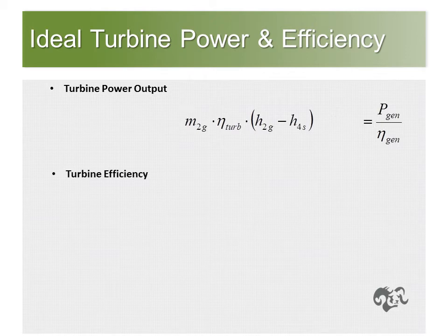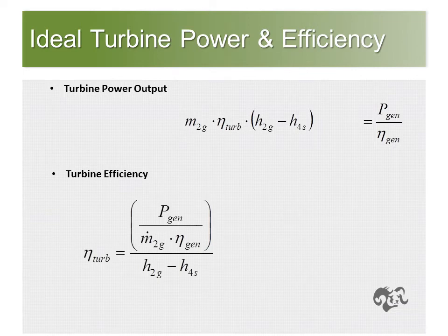Solving for the turbine efficiency gives this equation. You can use functions in the DCS where you only calculate this value when the unit is close to full load normal conditions, and then use a first order lag function with an extremely long time constant, so that this calculated value only changes very gradually over a time frame of weeks.